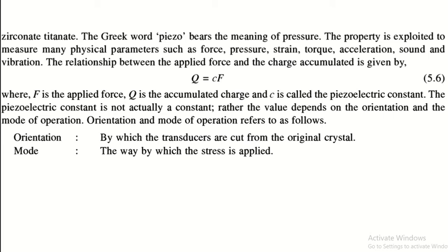The piezoelectric constant is not actually a constant, rather the value depends on the orientation and the mode of operation. Orientation means the way the transducers are cut from the original crystal. Mode is the way the stress is applied. So these two things are considered for the selection of the piezoelectric constant C.